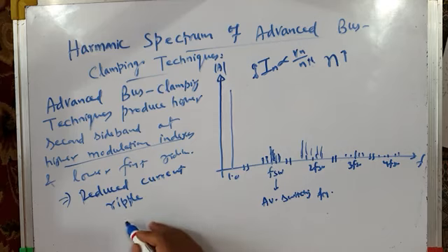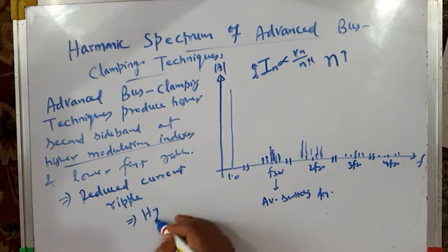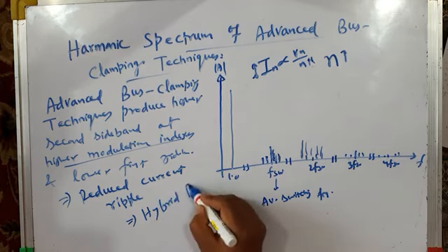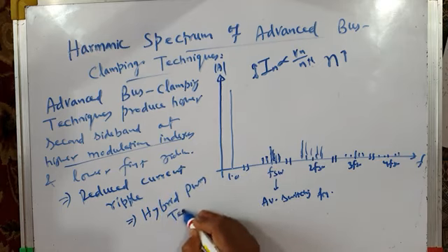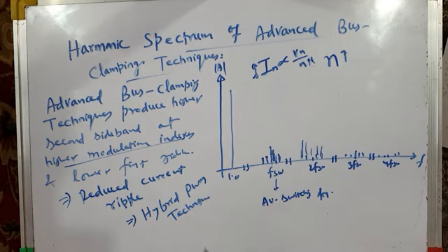Therefore, this gives us an idea about hybrid PWM techniques. What do we do in the hybrid PWM technique? If your inverter is operating at low modulation index, we have just a few moments back found that at low modulation index, the conventional space vector based PWM technique gives lower weighted THD. So we can operate our inverter with the conventional space vector PWM technique.